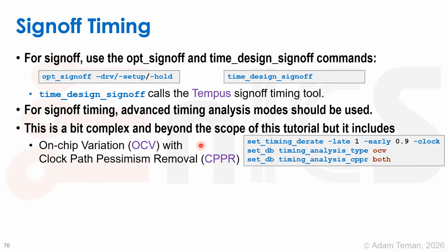For example, in setup, it's going to use a slow corner for the timing libraries of the cells for your launch path, and a fast corner for your capture path. It isn't actually that clear from the manuals, but I think that if you do add the timing derate, it will override that, and they won't do the two of them together.